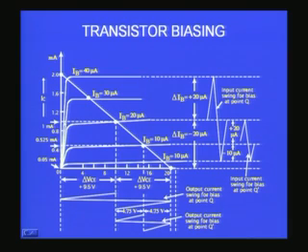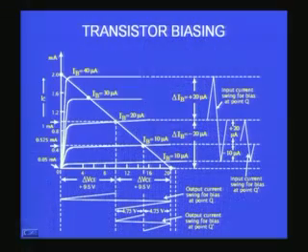So, the effect of this alternating voltage is to vary the voltage I applied at the base slightly by the amplitude of the AC signal. So, when that happens, you would find my base current can vary according to this change. So, when the base voltage together with the AC applied voltage increases, I will move along this line and go to maybe a new position corresponding to IB equal to 30 microamperes.